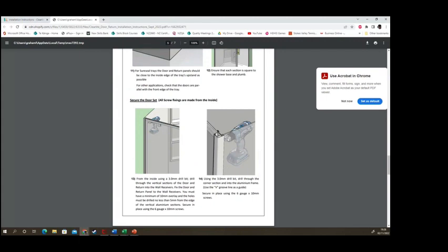The other thing that's good to have is a little mini different drill bit set. So if you break a drill bit, you've got the spare one, it's the right size, because if you oversize it, the screw won't go in, or if it's too small, the screw will snap because it's got too much stress on it. Stainless steel screws are quite brittle, so when they snap, the head just snaps off, stuff like that.